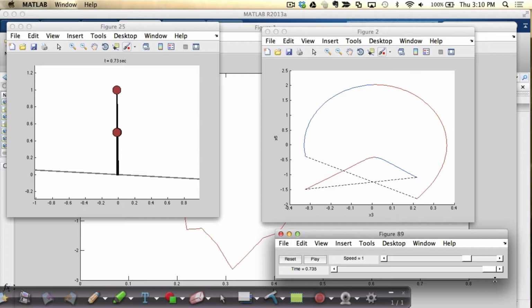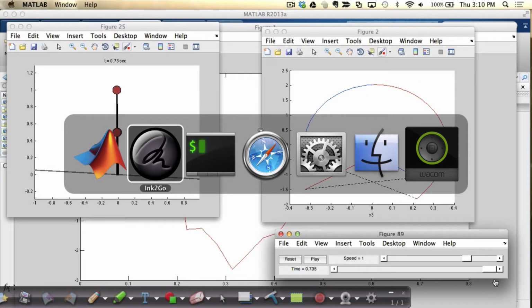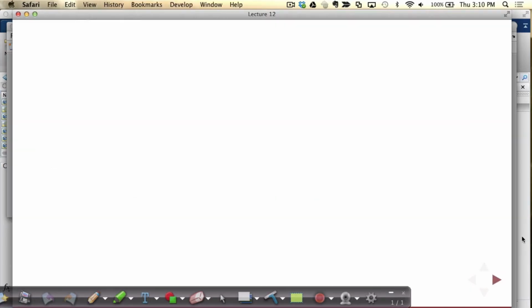And the key observation, I wasn't going to go into the details, but the key observation is that instead of writing it down exactly like what we've written down, you write it down as a system that has control, the contact force is always being an extra decision variable, and you try to solve for the constraint forces at the same time as you're solving for the original system. And that's allowed us to think of it as sort of a single mode system, if you will, where the forces now are either active or not active, depending on if the constraints are in play. And I was just going to show the highlight reel for that.